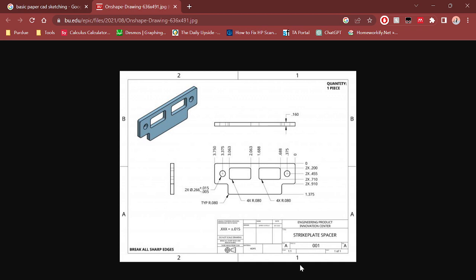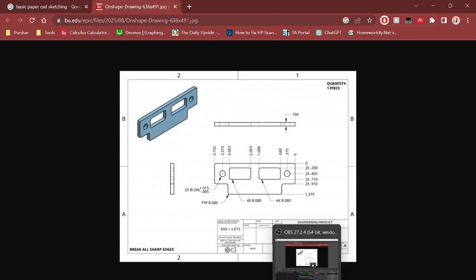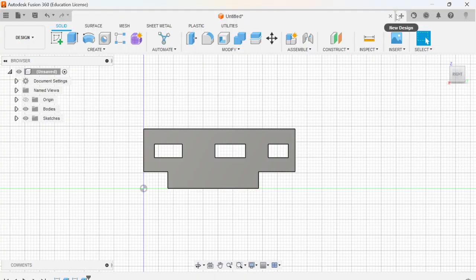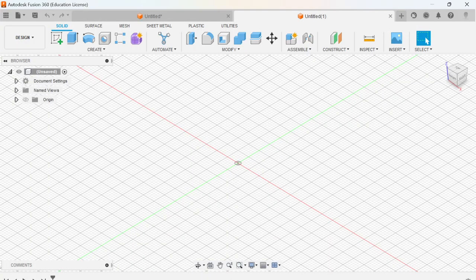But if I was trying to design that, you can see how I took that approach. I started from the side view, I extruded it lengthwise, and then I added the details. So for the theory of CAD, the best way to design parts is to start from the faces that have the most detail. So the best way to design this part is going to be this way.